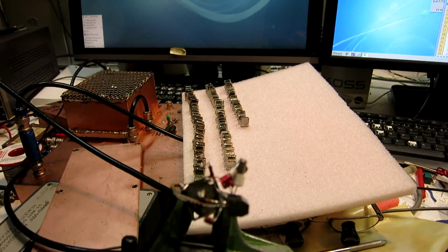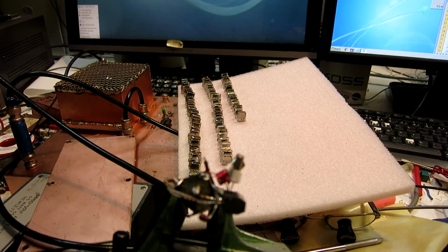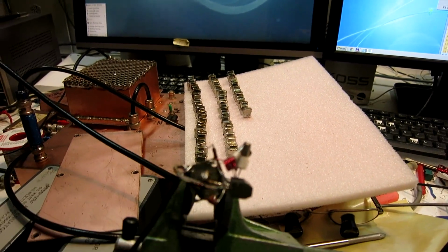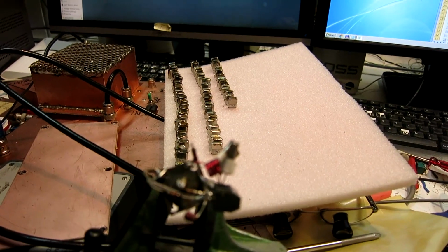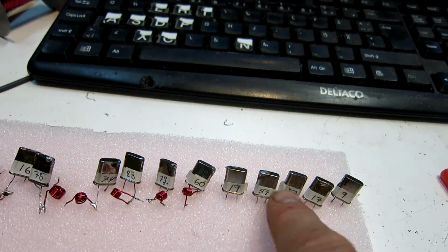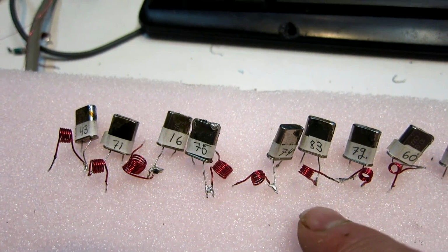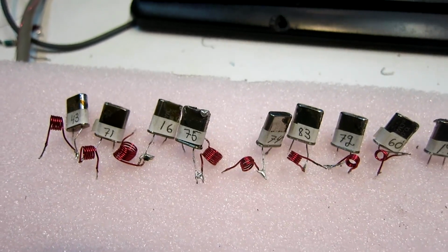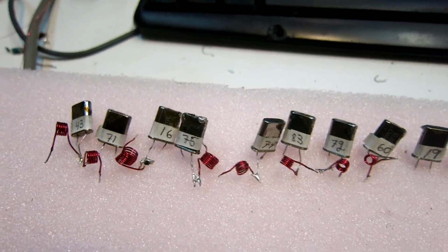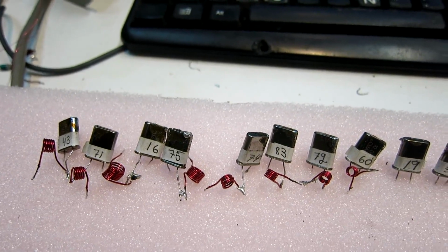I could have used capacitors, but the only capacitors at appropriate values that I have access to are ceramic capacitors, and they are often noisy, so I don't want to use them. An inductor is perfectly noise-free, so that is safe. These crystals have nearly the same frequency. These other ones need an inductor in series to bring the series resonance to that same frequency. So I have adjusted the coils to make all these 13 resonate at the same place within plus minus 30 hertz or something like that.